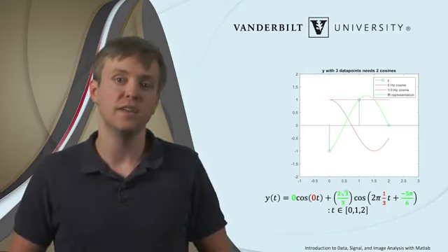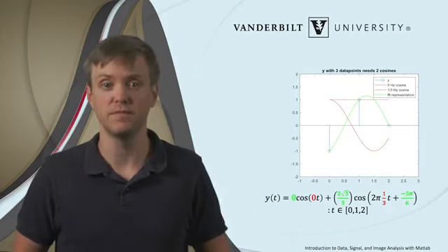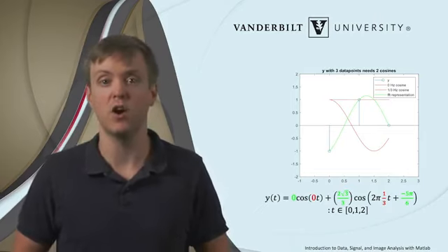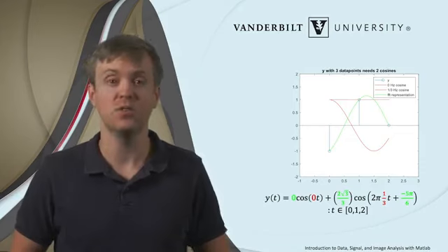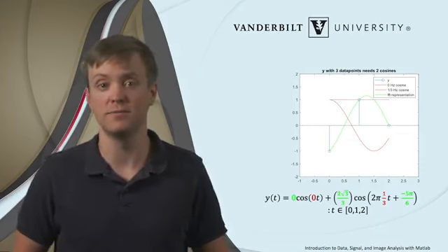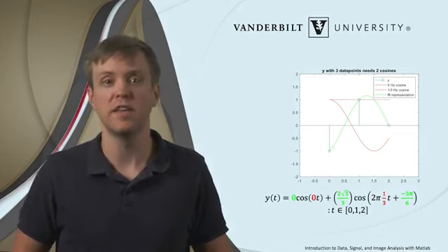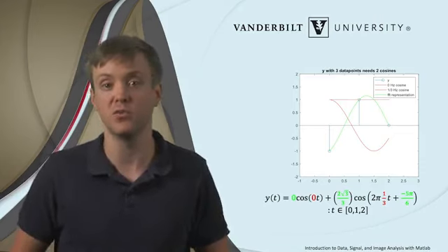It is noteworthy that our IFFT cosine representation is defined by 3 numbers. The frequencies of the cosines, shown here in red, are predetermined by the sampling frequency and the number of data points in y. The actual values in y do not matter. No matter what values y takes on, they can be represented as the sum of cosines of those predetermined frequencies.